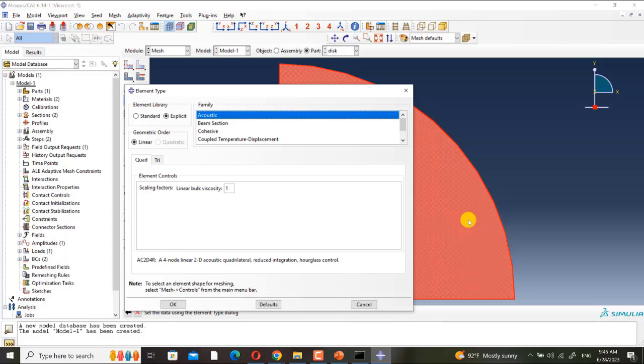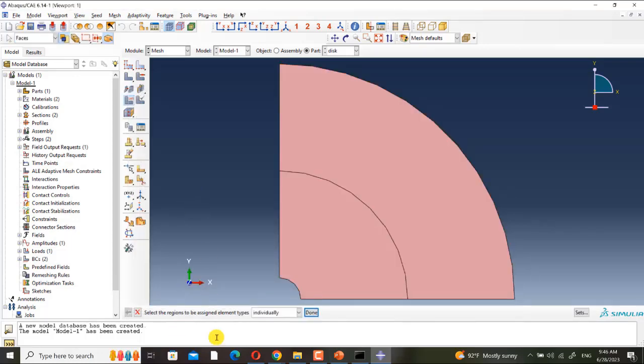If I also set it to plane strain, then I cannot detect the region in the INP file because all of them are the same. But when I change the element type in the CAE, it is also changed in the INP file, and I can detect it simply. This is a trick.